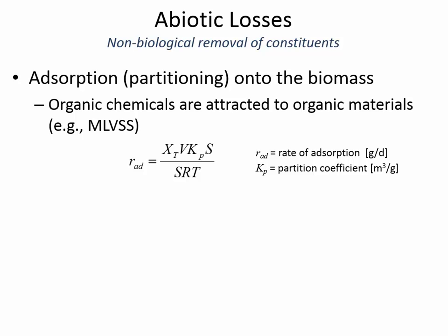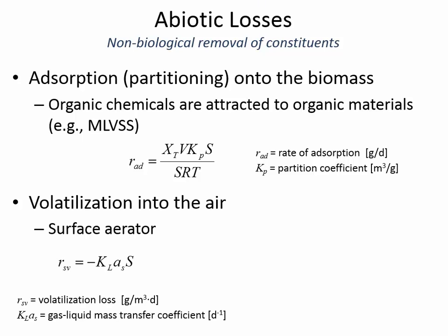It's a block of porous carbon, and so I didn't feel so worried about drinking the water, although they said it never got bad where I live, because I don't live in Charleston. But so here, in a wastewater treatment plant, the biomass, the mixed liquor volatile suspended solids, MLVSS, can act as a surface that some of these organic compounds just naturally sorb onto. And so what this rate here is showing is the rate of absorption. It's the chemical not being eaten by the bacteria, but the rate of the chemical just sort of absorbing onto the surface of the biomass.